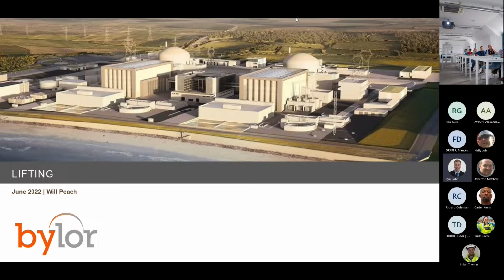Yeah, so we've worked together with the software developer for the scanning system to develop that. So it identifies the plates, I think, effectively automatically. Some of the other types of embedments need more manual work, but you get a point cloud, and it takes photos as well as the point cloud, so it looks visually like a 3D room to work from. And obviously you can slice drawings from it.